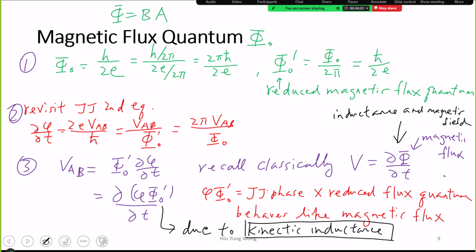In your regular design, you also have kinetic inductance. But because it is at room temperature, it will die out easily through scattering. And that's why your geometric inductance will dominate. But in a superconductor, the kinetic inductance usually dominates. Okay, so this part, maybe I don't say it well, is a little bit confusing.